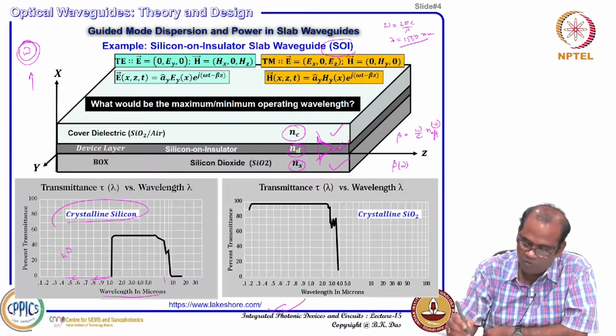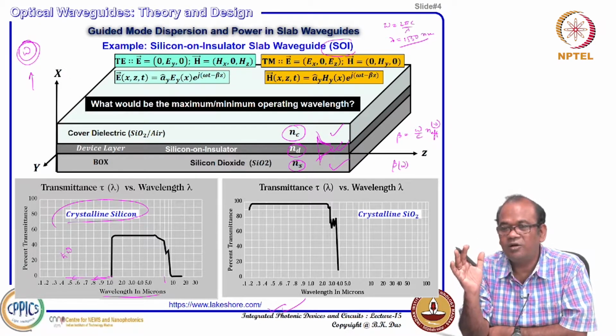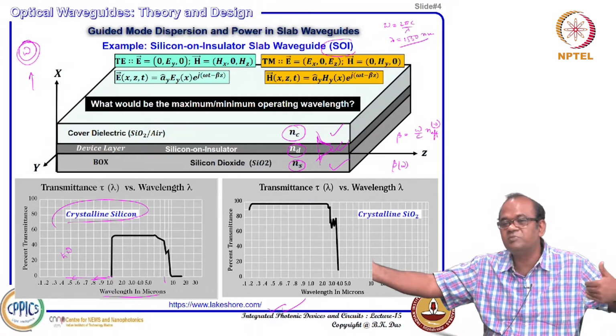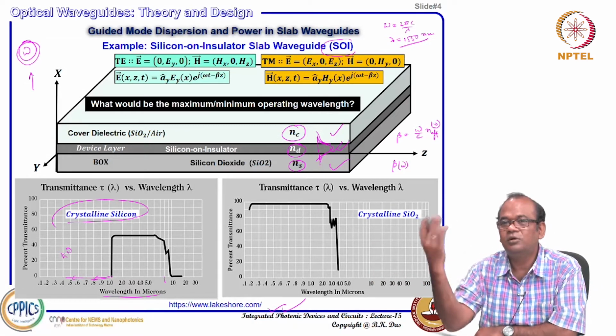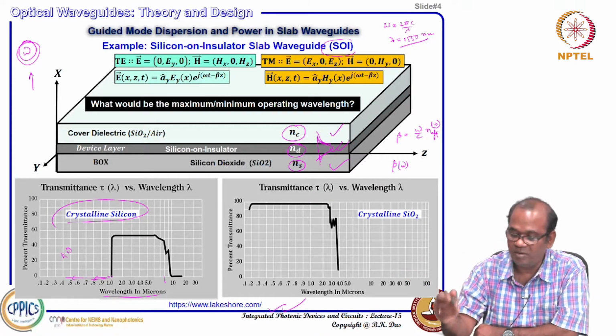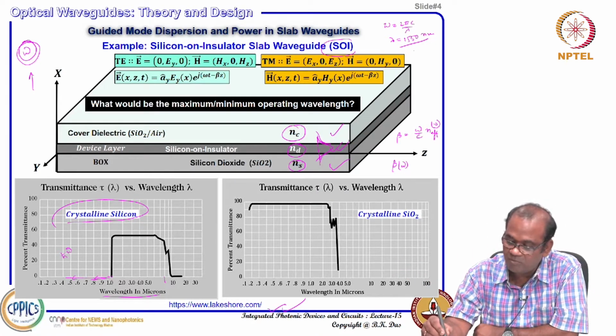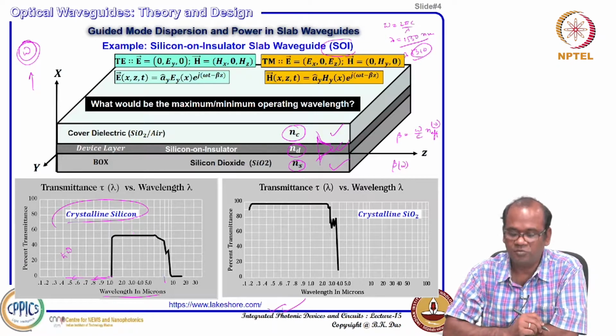That means, for the core layer, as far as transparency is concerned, the electromagnetic wave has a broad transmission spectrum. So, you can use anywhere from 1.1 micron to 10 micron. Within that, remember that we have the third generation communication window as well as the second generation communication window, 1310, also falling within that. So, they are transparent. Okay.